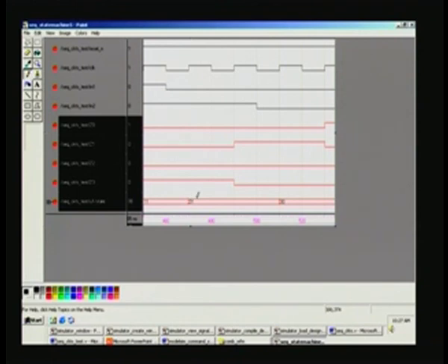So, naturally that state output must get reflected only at the positive edge of the clock. Any sequential machine will have this always delayed by a clock, and that is not a handicap, because we always have a very high frequency for the clock, and no user can notice the difference, and no erroneous operation can take place, because the whole thing is synchronous as such.